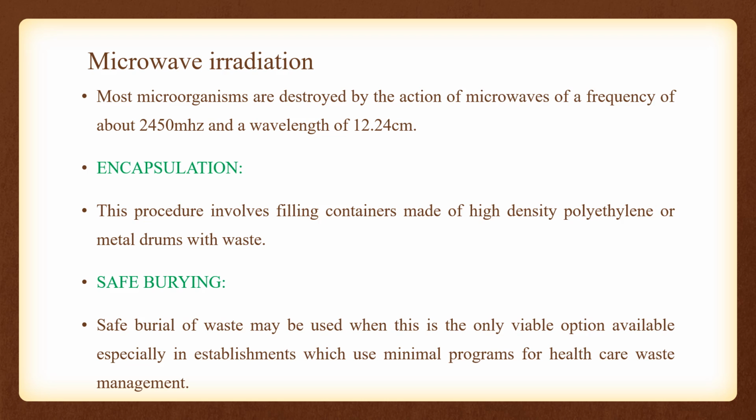The burial site should be lined with material of low permeability like clay. Only hazardous healthcare waste should be buried so as to conserve space, and large quantities of chemical waste should not be buried at one time to avoid environmental pollution. The burial site should be covered with a layer of earth to prevent health hazards.